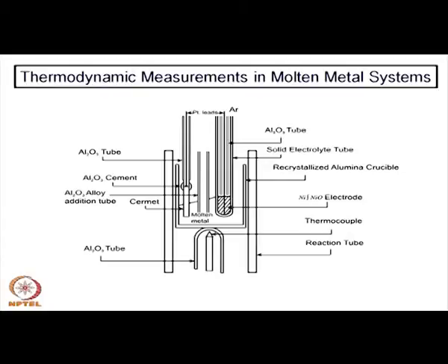Okay. Now, this also at a particular temperature has a definite oxygen partial pressure, just like an equilibrium partial pressure between metal and metal oxide. So, nickel when it oxidizes to nickel oxide at a particular temperature corresponds to a specific partial pressure of oxygen. Whenever there is a coexistence of nickel and nickel oxide, a specific partial pressure is thermodynamically maintained.